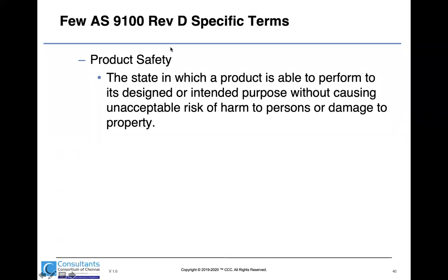We could say, when I'm doing just small machining of a component, I'm trying to meet the drawing specification. So when I'm handling this product, unfortunately or mistakenly, I've dropped the product on the floor. But how are we going to deal with these types of products? Is this a non-conforming product? Who is going to identify it? Dimensionally, as per the engineering drawing, the product is perfect, but I have dropped it on the floor. So how about the reliability of the product? These types of questions we need to ask when we are establishing an aerospace quality management system.